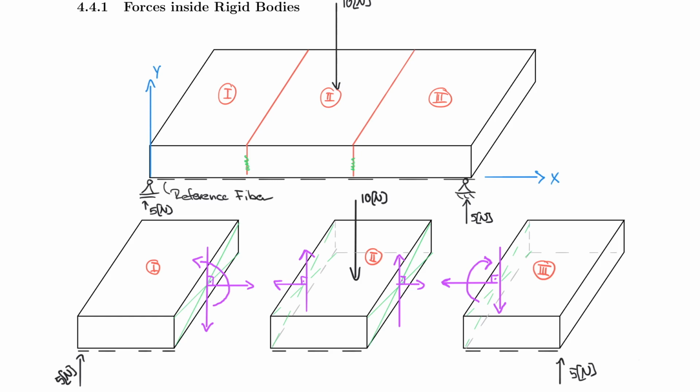So therefore you understand that this is not really in equilibrium yet, because on the left side to it you have a bending moment that is also presented to the cut, and on the other side as well from element number 3. So we need to balance this rotation and we need to balance this rotation. In other words, I need something that resists bending here in the glue, and I need something that resists bending there.